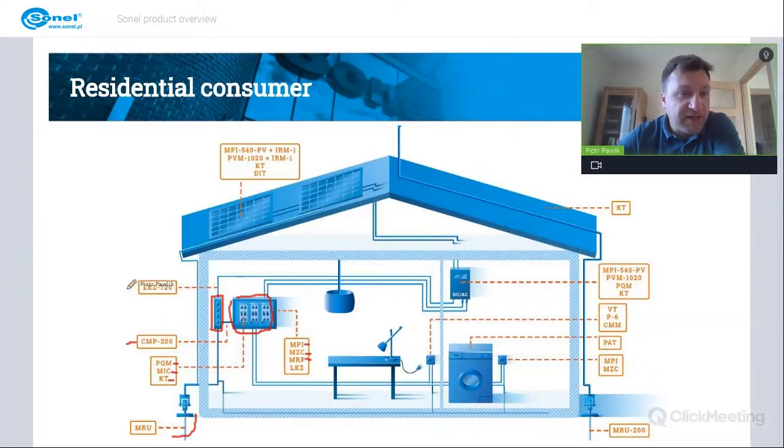we can use LKZ720. Also, we can use this LKZ720 to locate a particular switch which is connected to a particular outlet. So in this situation, we put the transmitter in the outlet and we look for switches on the main board. Also, with LKZ720, we can check if there's any breaks or shorts in the cables in our building, in our walls.